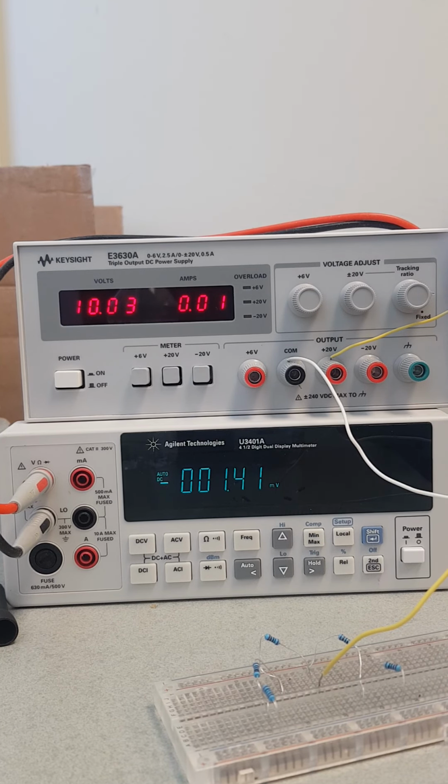So what does this lead us to? The tolerance problem in the resistors can be very significant when the change in the resistance of the sensor is very, very small. This is applicable to a sensor like the strain gauge. As you will see in the videos that come after this, the actual resistance goes from the original 120 to 122 or 123, so you have only a 2-3% change.